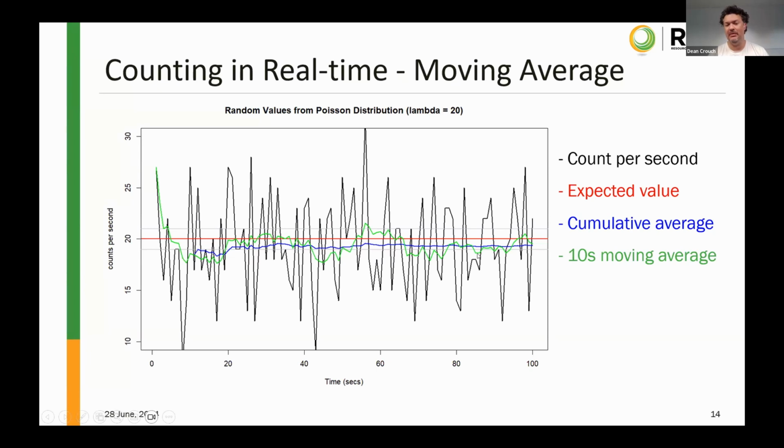This is probably what your meter does. It doesn't look at everything it's ever seen. It's going to have some window. Sometimes you can control that window. The old meters used to have a fast and a slow switch. Fast was a very small window, so the meter would respond quickly to any changes, but it meant that if you were in a low dose rate environment like this, it would bounce all over the shop.